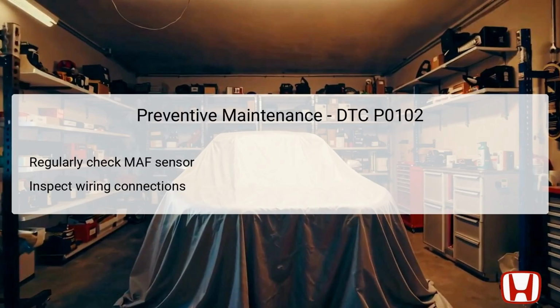Taking proactive measures can help prevent issues that lead to DTC P0102 in the future. Regularly checking the condition of the MAF sensor is a vital aspect of maintenance. This includes inspecting for dust, debris, or physical damage that could affect its performance. Additionally, ensuring that the wiring connections for the MAF, IAT sensors, as well as the ECM, are secure and free from corrosion can significantly reduce the risk of electrical failures.